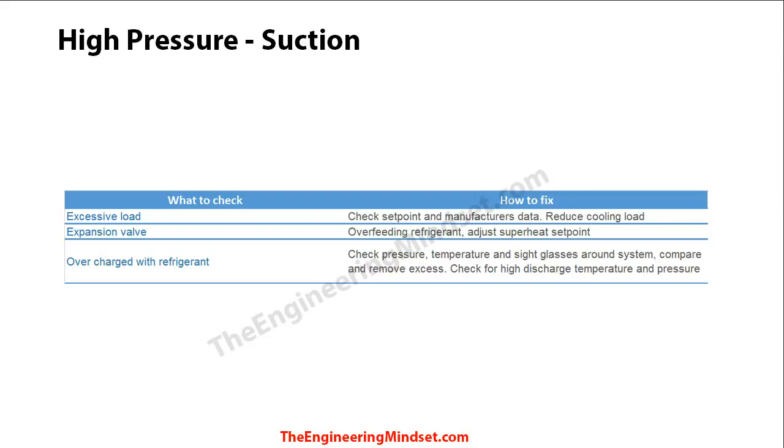And then again, as previously mentioned, it could also be overcharged with refrigerant. So you want to check your set points and temperatures and pressures around the system. And then if that is the cause of it, then you want to reduce the refrigerant in there to remove some of the excess refrigerant.